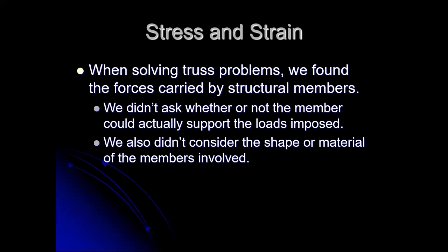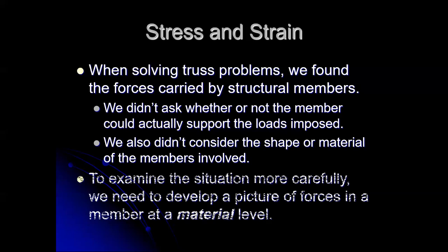How big or small these things are that we can get away with. Shape didn't matter in doing truss analysis. It didn't matter whether we used a round beam or a rectangular beam or an angle bracket. The shape didn't make any difference because the material had infinite properties. We considered it to be essentially as small as we'd ever need it to be. In fact, we drew it out on most of our drawings as straight, very thin lines. Real materials have to have some dimension to them, some size, some thickness, and that plays a pretty big role in terms of stress and loading.